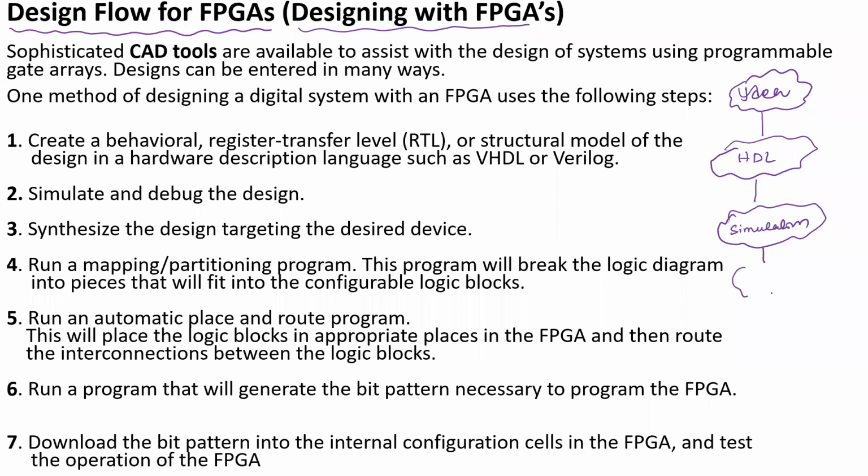Next, once the simulation is completed, we have to synthesize our code. What do you mean by synthesis? Whatever the HDL code is, that code will be translated into FPGA-related hardware.